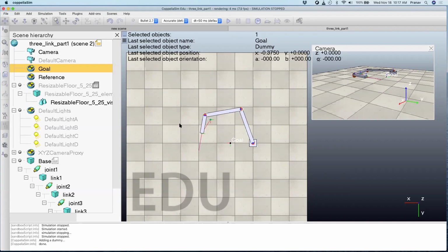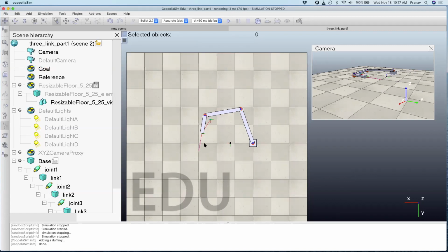Okay, now we also, as I said, instead of moving the block, which I'll put over here, directly from left to the right, I want the manipulator to pick it and take it here and then go down. So this is actually this point which I'm going to create. In robotics, it's called a via point. Via point is because you want the manipulator to go from A to B via C, so that it doesn't collide with anything else.